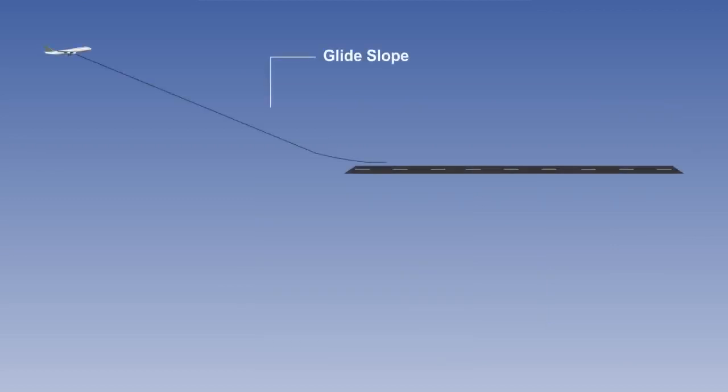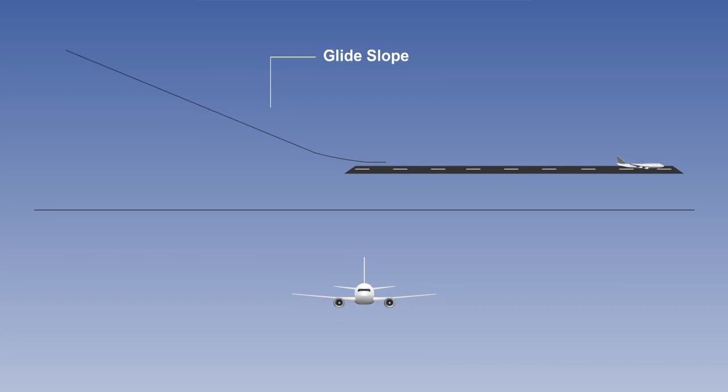Mode 6B adds two further safety features to the GPWS system and consists of height callouts on approach and bank angle alert. 500. 100. 50. 40. 30. 10. Bank angle is to warn crews of excessive roll rates.